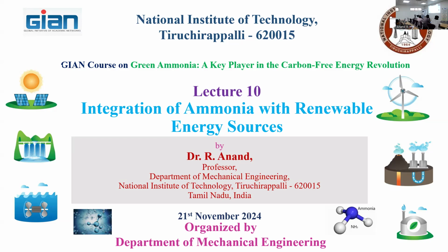This vapor is considered the working fluid for producing power using the work-producing device called a steam turbine. Then again it goes to the device called a condenser, which converts the vapor into liquid. Then the same water can be utilized again and again. It's a closed circuit.